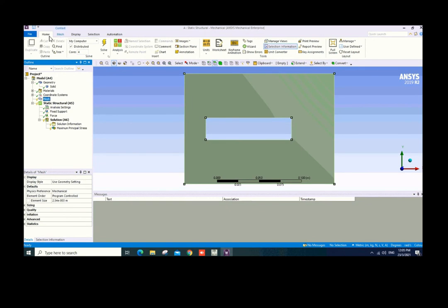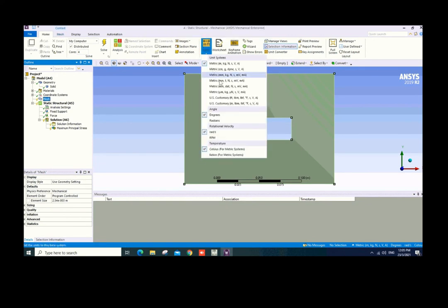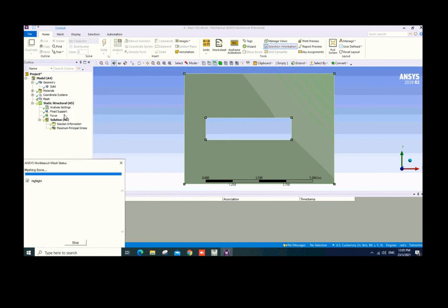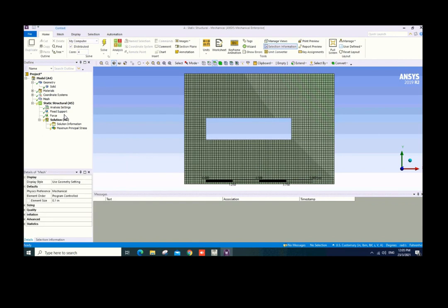If you look into the unit itself, you can change it to whatever you're familiar with. So I put 0.1 size, based on the tutorials. Then I can regenerate the mesh. Because just now we opened Design Modeler, the system thought that we have changed some things, so you have to re-update everything again.